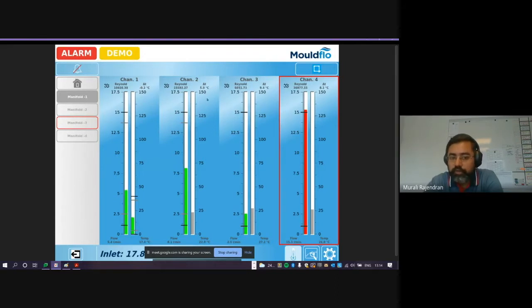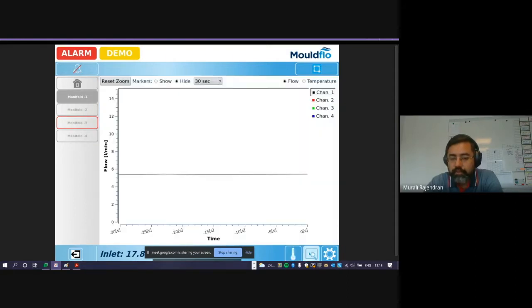And this we call the manifold overview screen. In the manifold overview screen, we get all the different information with regards to the manifolds, like the temperature, the outlet temperature, the flow, the delta T, the Reynolds number, and pressure if pressure sensors are enabled. And you can see there are three icons at the bottom. The leftmost icon at the manifold level is the manifold overview screen. The middle icon is the same view but in a timeline based manner.